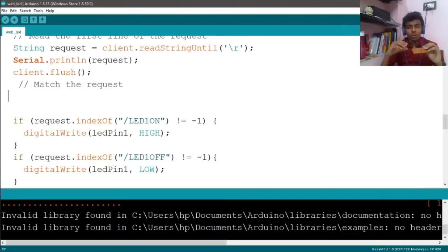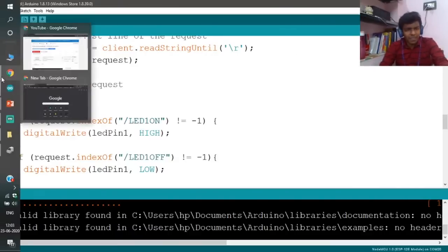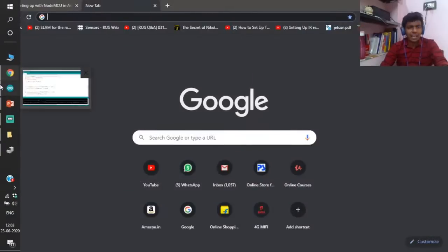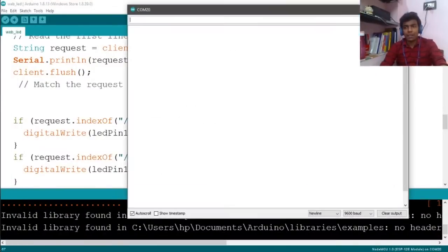Okay, if you need to use it with a relay connection, like any kind of external relays, so if you need to control a real fan or real light, you can purchase any channel relays. You can connect this input pin to the relay's input. On the output side, you can connect the 230 volt as well as the fan connection on the NC and NO, so that it will be connected to real-time home appliances with the same network and same program.